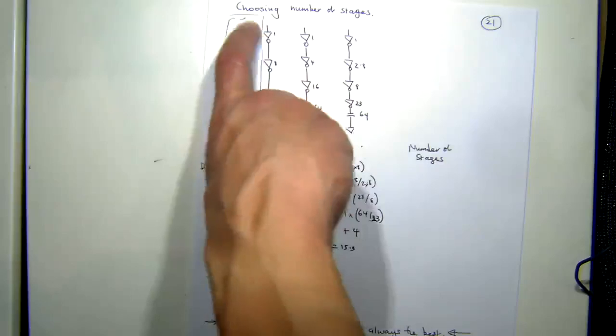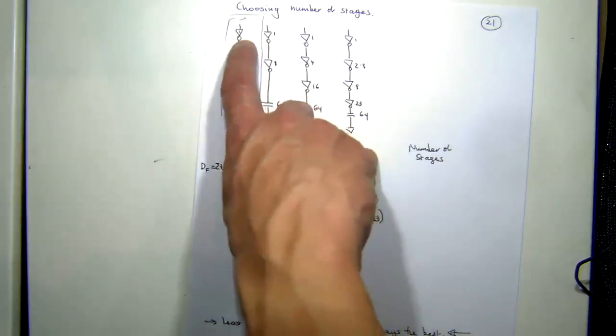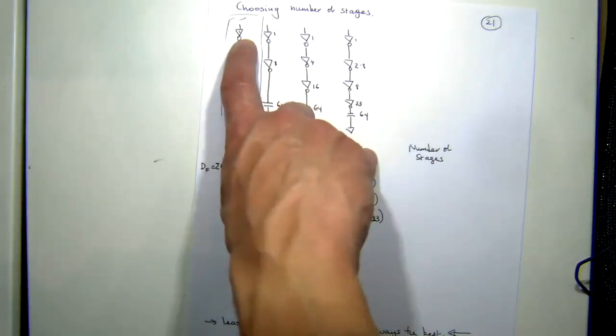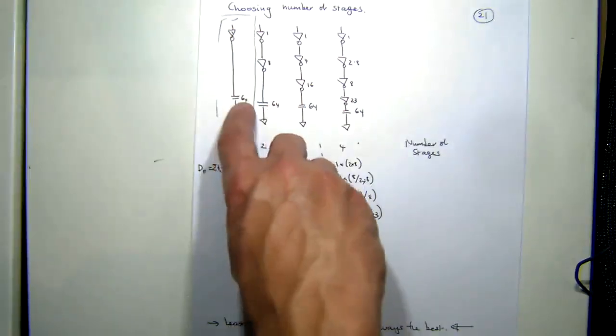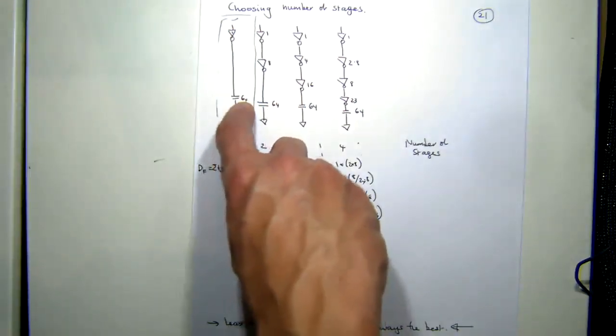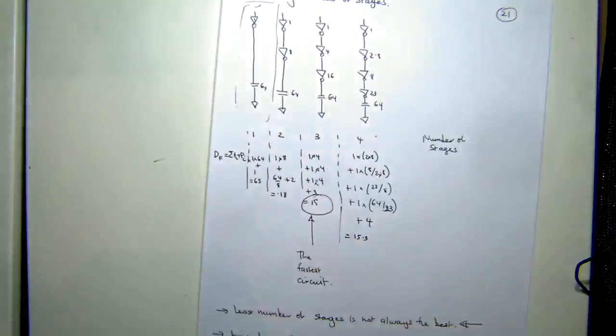One important example is trying to drive a clock. You can say, well, I'm inverting it, but that doesn't really matter, that's just changing where the edge transition occurs. And you're driving 64 registers. Which one of these would actually be the fastest? That's one of the examples.